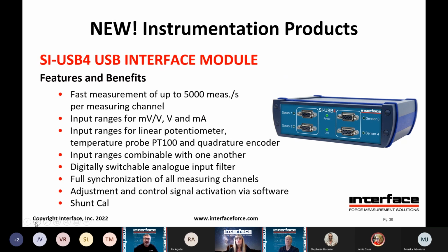It can take analog inputs like 4 to 20 or VDC, so that could come from like an LVDT or pressure sensors or whatnot. You can take encoder inputs and VDC, so you can do torque, angle, speed, power calculations. This is a USB interface to the PC, and it comes with software to view and graph and log the data. Next slide.